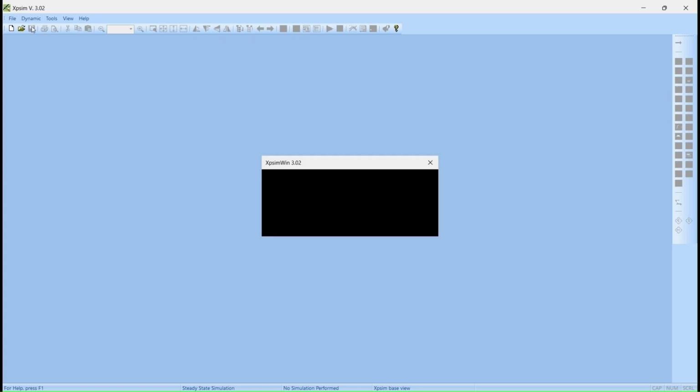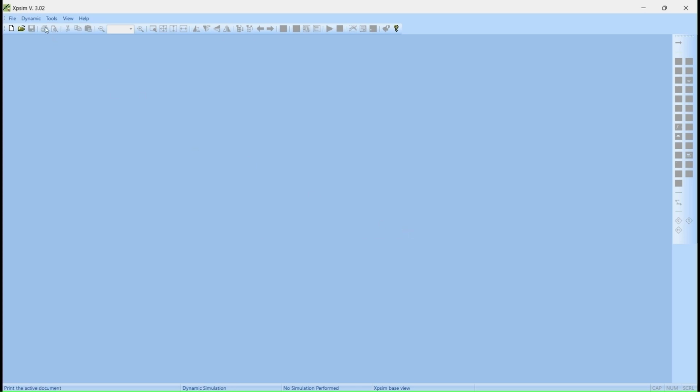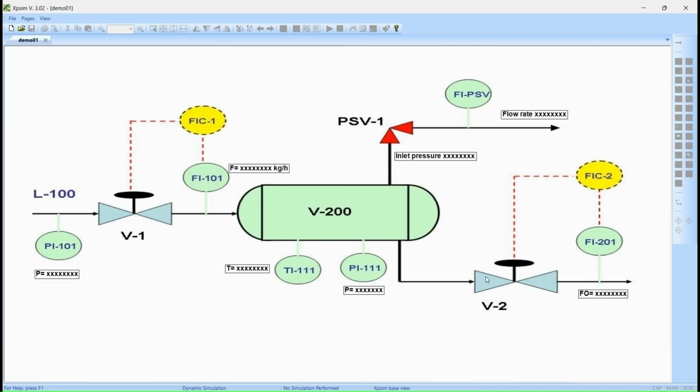Before the pressure safety valve simulation presentation, a short example of the use of process and instrument diagrams is presented. Process and instrument diagrams, generated with any chemical engineering design tool, saved as a .jpeg file, can be added with tags defining connections with instruments created in the dynamic simulation input file.